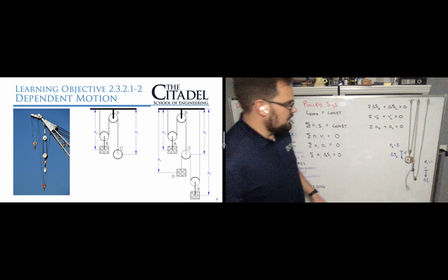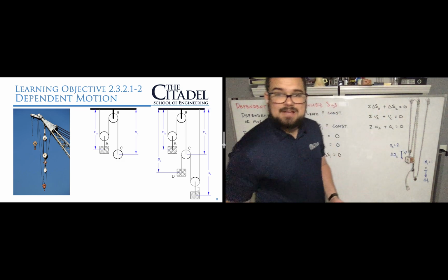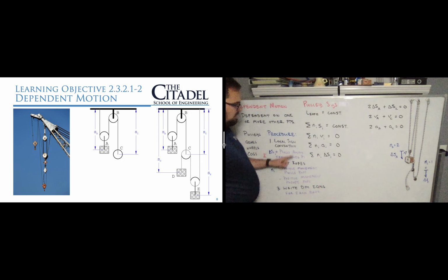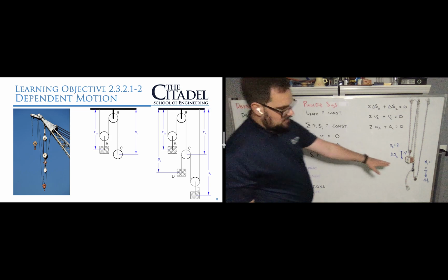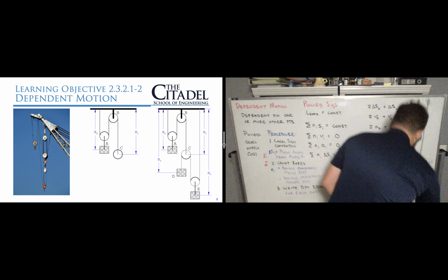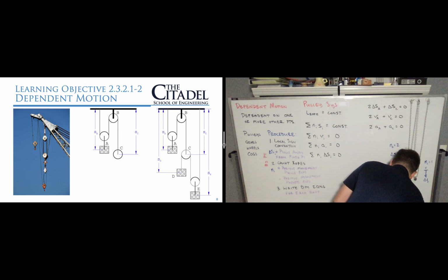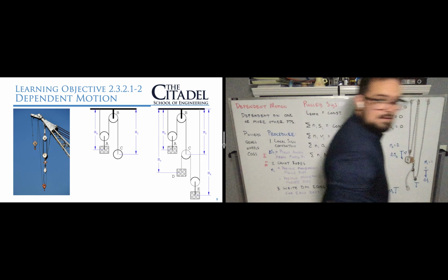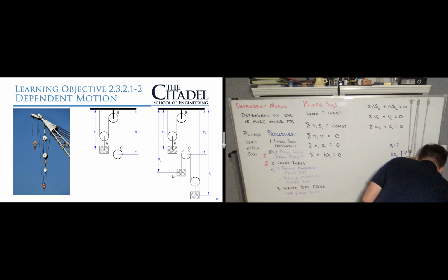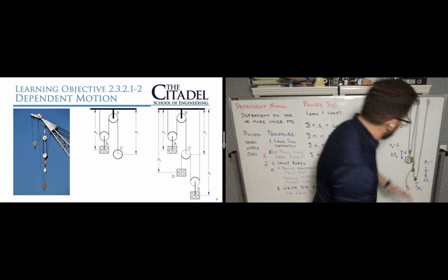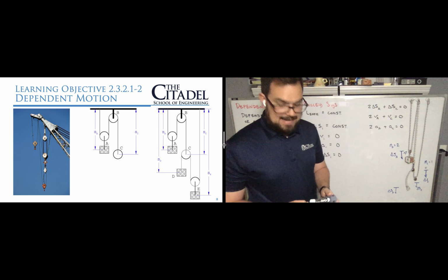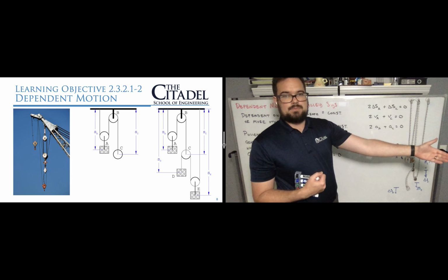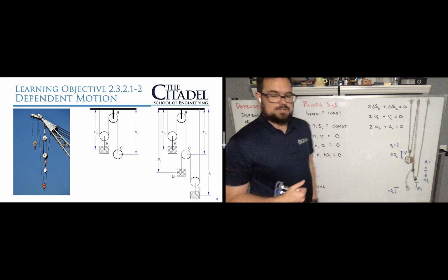Over here at C, when I move point C in the positive direction, I'm going to be pushing ropes. So I've already set up my local sign convention, starting at the top. Delta C is good. We call this point D over here, delta S_D, and where the pulley is, that's delta S_E. In each case, the closest fixed position is still up here at the top, so positive is still down. This is going to be useful on one of your homework problems where there's a weightlifter pulling sideways. There's a fixed point away from them on the weight machine, and positive is away from that, so away from the closest fixed point.